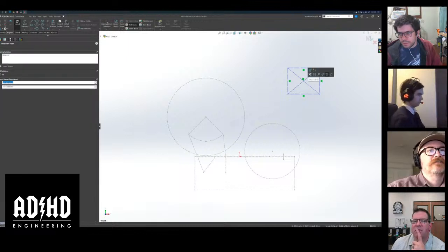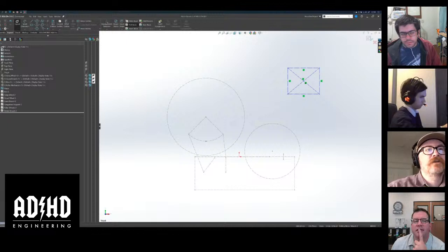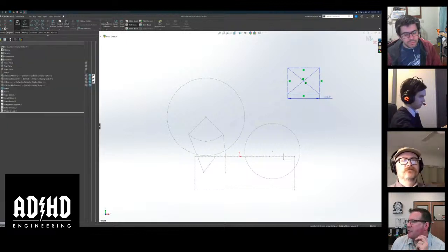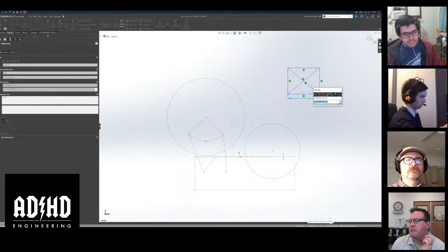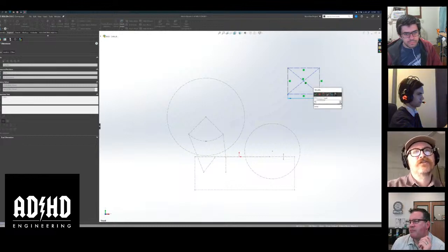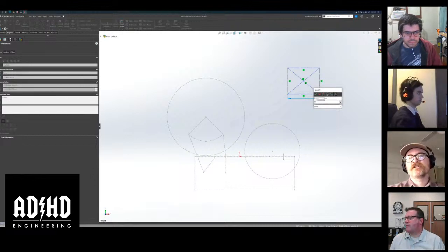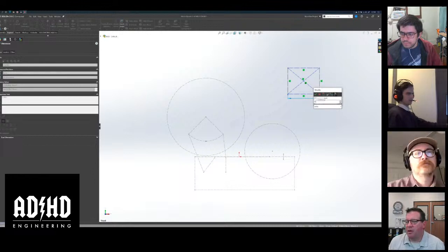Like that? Well, I haven't actually dimensioned it. What is the dimensions? So the motor outside for a NEMA 17 motor is 42.3. From the hole to the hole? No, from outside of the motor. It's 31 millimeters from the hole to hole, but I thought we weren't going to do the holes. Well, that's actually a perfect, I would say the relationship from the bolt hole circle to the shaft is the whole reason that I made it a... Yeah, okay, so then do 31 millimeters.